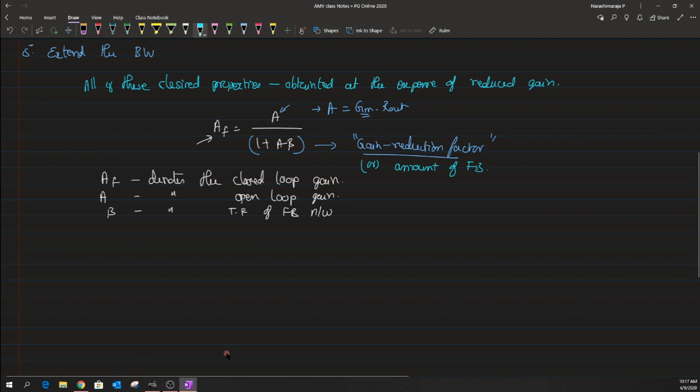Okay, now under certain conditions, negative feedback in an amplifier can become positive feedback. So even though this particular feedback that I have written down here represents a negative feedback gain expression, sometimes this negative feedback expression can become positive feedback, and it may tend to cause oscillation at the output, and the circuit might become some sort of unstable circuit. Okay, but we will discuss these conditions in the later part of the syllabus, when we discuss stability and compensation techniques. Okay, but here we are interested only in the design of stable amplifiers.